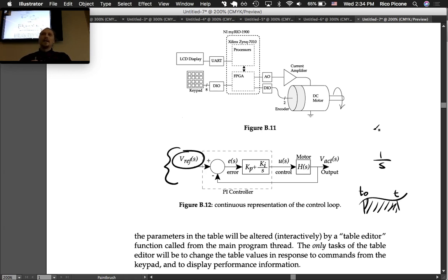We can talk about why that is, but it's essentially because the derivative estimation is very prone to noise. You have your measurement data points of your error coming in, and maybe it's noisy or something weird happens, and suddenly there's a point that comes in that's way down here. Your derivatives are the slopes, right? Slopes are pretty pedestrian, and then suddenly you've got this slope that just falls off at a rapid rate. And so suddenly you would have this huge response that you would put into the motor using your amplifier, and you would drive it with a ton of current.